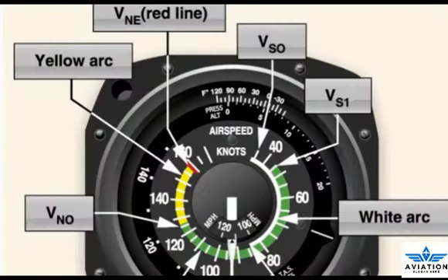Aircraft weighing 12,500 pounds or less, manufactured after 1945 and certificated by the FAA, are required to have ASIs marked in accordance with a standard color-coded marking system. This system of color-coded markings enables a pilot to determine at a glance certain airspeed limitations that are important to the safe operation of the aircraft. As shown above, ASIs on single-engine small aircraft include the following standard color-coded markings.